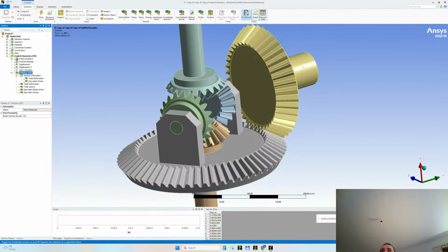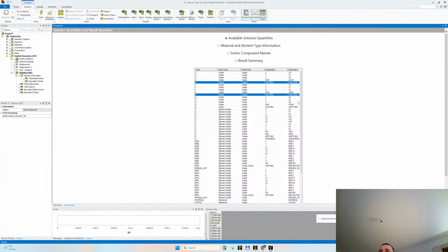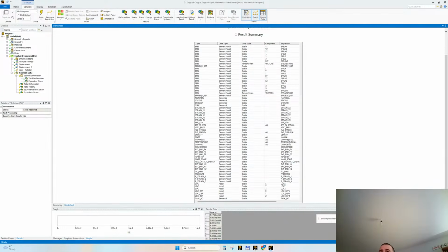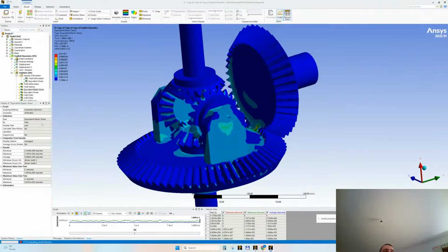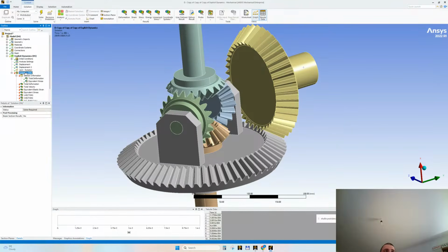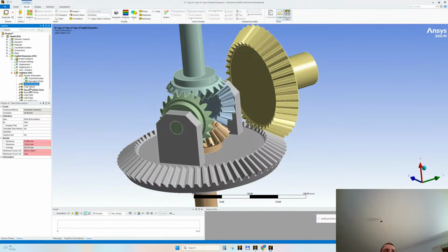And here, worksheet, U vectors, V vectors, the vectors for displacement and velocity, and also, as usual, energy. Do we have some temperature? Let's see. And pressure. Right-click, create user-defined results, evaluate all the results. I asked too much.